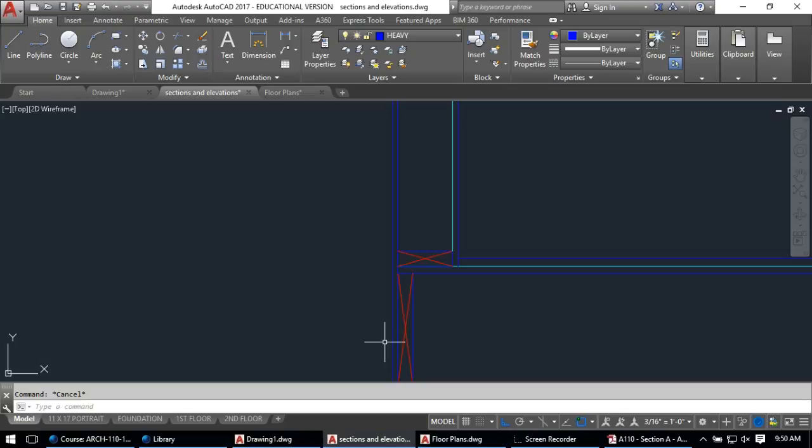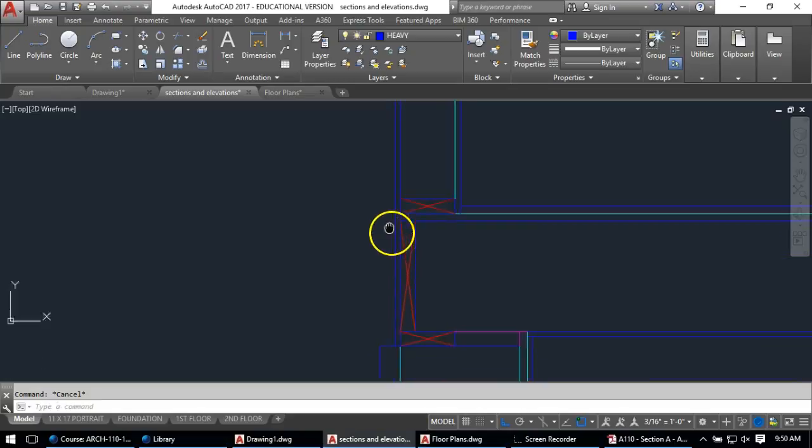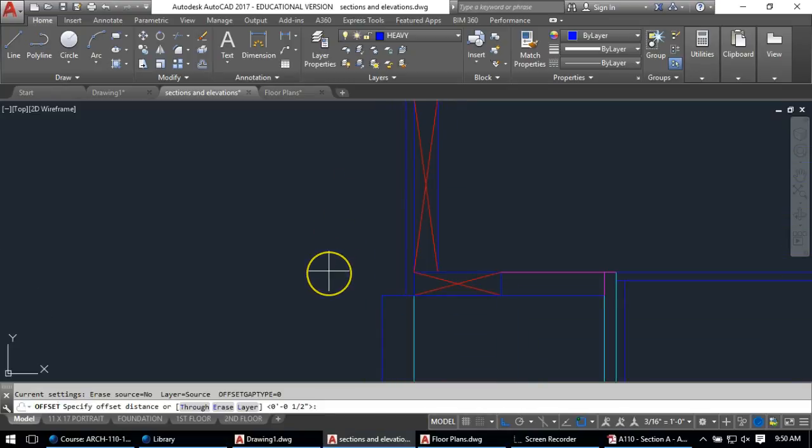And there also looks like there is some skirt board, something there at the bottom. Let's see, one note says 5/4 by 6 inches. Okay, so I'm going to offset 5.5 inches up, which will be the top of that, and out 5/4 of an inch.